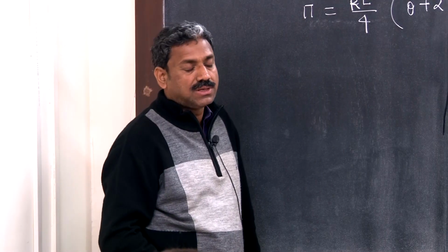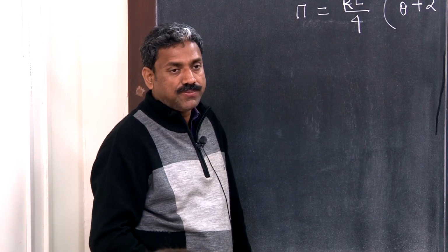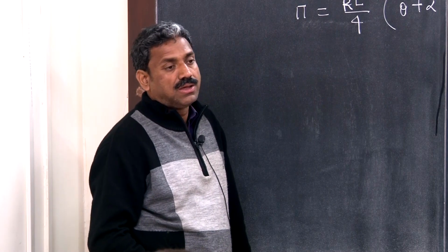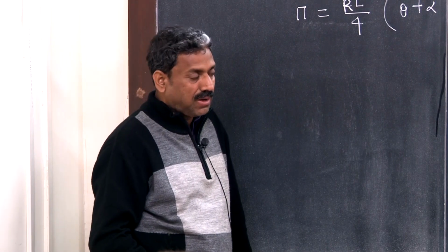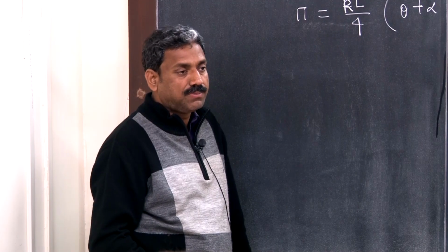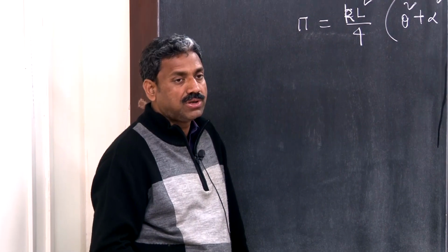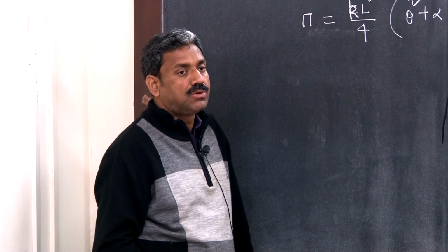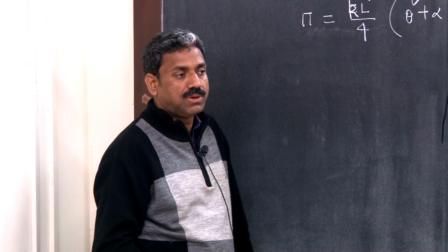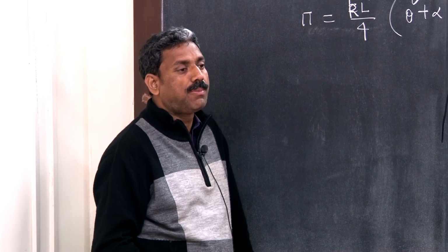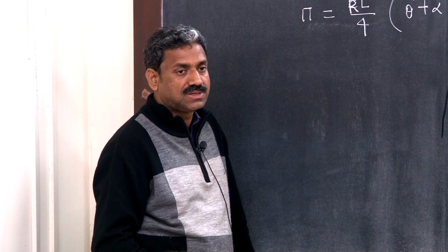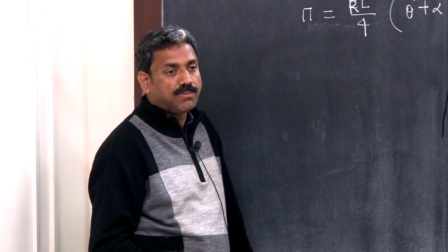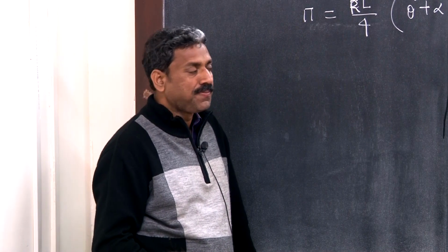We have demonstrated the bifurcation stability diagram, and on incorporation of imperfections, the equilibrium path for the imperfect system will asymptotically approach the perfect system, and the system shows notorious imperfection sensitivity that we have demonstrated. It follows the half power law, Koiter's imperfection sensitivity. That means if there is slight imperfection, there is a significant drop in the critical load.